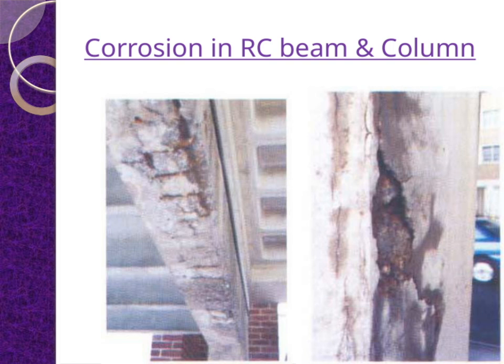When the steel inside the concrete starts to corrode, it produces rust, which expands and creates internal pressure. This pressure can cause cracking and spalling of the concrete surface. You'll often see this as rust stains or flaky concrete on the surface. It's important to understand that corrosion not only weakens the steel, but also affects the overall stability of the structure. In beams, this can lead to reduced load-carrying capacity and potential failure under stress. In columns, it can cause instability and even collapse if left unaddressed.